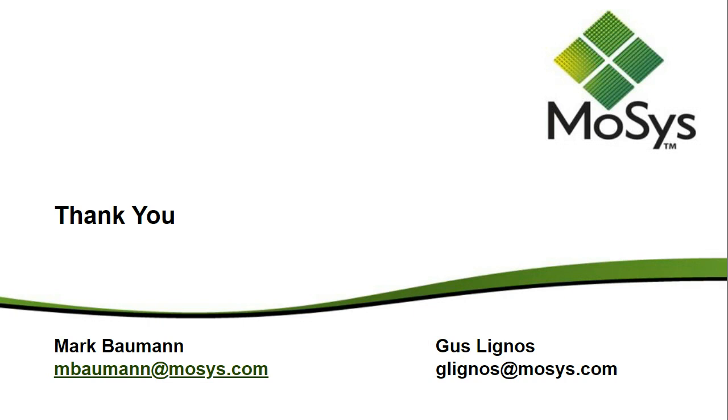Our first question for you, Mark, or for Gus, depending upon who gets this one. Do you recommend necking down high-speed trace width only in the breakout area and then increasing their routing width to reduce loss of skinnier traces, even though this creates a discontinuity? Yes. In the examples that we've done, yes, we want to minimize the amount of time that the traces are at that 4 mil or the minimum trace width, and then widen it back out as soon as we can, and then try and balance it again lengthwise by doing that wiggle pattern kind of thing.